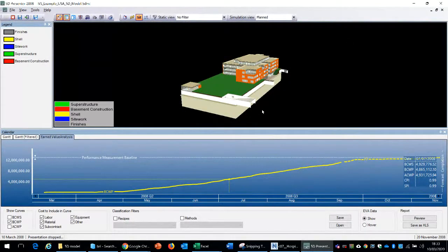So this is an example of a 5D model, and now in future we will see a great deal of integration taking place between this. Now it doesn't stop here. We are seeing augmentation of this model with 6D and 7D, with people bringing health and safety data and risk data into the model. So adding different layers of information to an extent that now we have started using nD modeling. So it could be basically any number of dimensions. You can think of it as a GIS database. So you can have different layers of information on top of your cost, quality, time specifications.